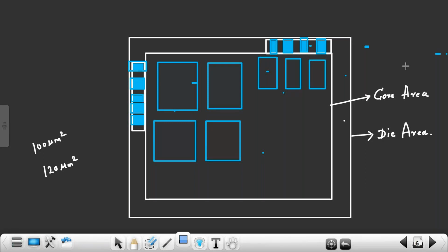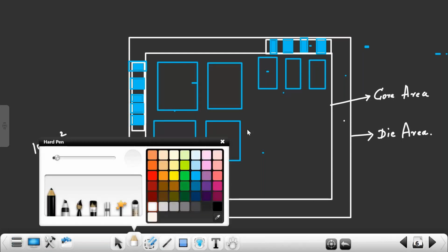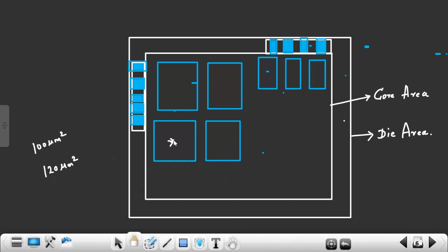I have a 100 megahertz clock. I want to increase it to a 200 megahertz clock. Then I want a PLL. So the PLL I cannot get through digital design. That should be done through analog design. So whoever has designed the PLL, I'll get the layout information from them and I'll place it in the design. So all these are macro layouts. All these are layouts of macros.